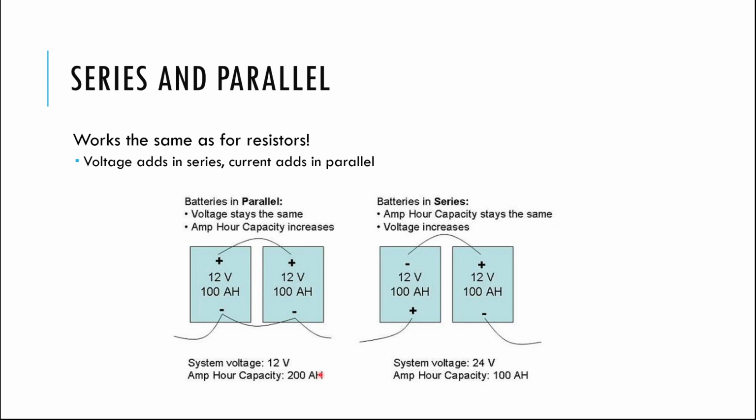We're multiplying charge per time by time, which means this is a roundabout way to measure the total charge stored inside of a battery. So, of course, if I connect two batteries together and you keep their voltage the same, I'm essentially doubling my capacity because each battery has a capacity maybe of 100, right? But if I connect them in series, I'm pulling all of that energy out through them together with a higher voltage, so the capacity stays the same.